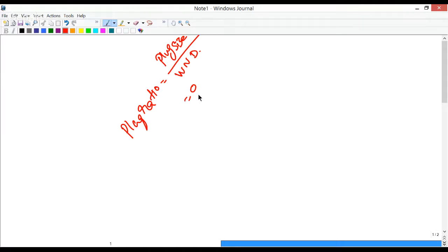The deterioration of copper electrode life while welding galvanized steel is mainly by the zinc diffusion. Right, so the galvanized layer is a zinc containing layer. The copper readily forms the copper zinc alloy. You can say the copper zinc alloy is commonly known as brass. So the brass formation is the main reason you have deterioration of copper electrodes.